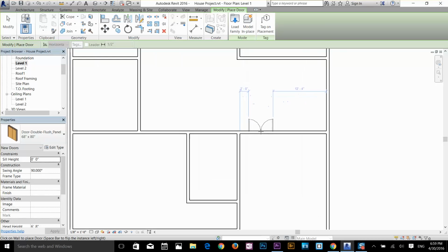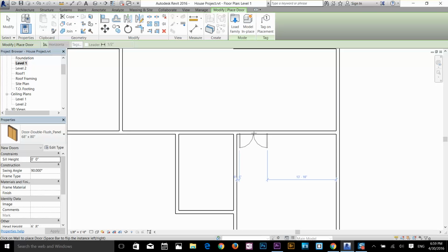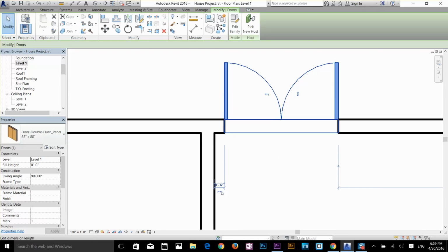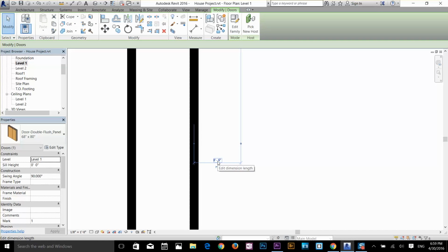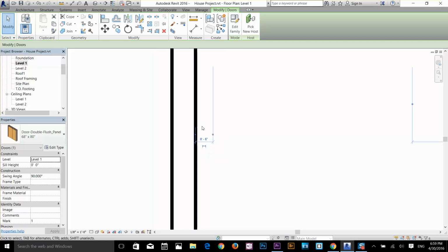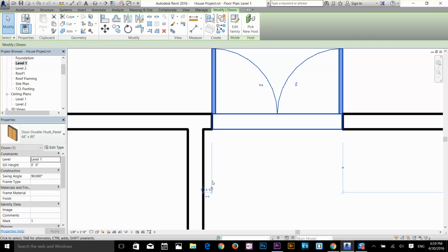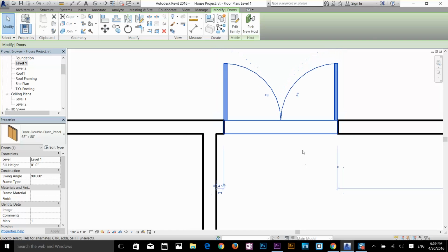And then I'm just gonna take that and I'm going to drop that about here. So just click here, your door's done, and now you click on the door, and here you got the dimension, how much distance you want to leave from this wall to the door. So I'm just gonna click here, and I'm just gonna get 0 space. 0 is actually your feet, which is 0 now, and space will jump to the next dimension, so that would be 4.5, and I'm gonna enter. So now the exact distance from this wall to here is about 4.5 inch.